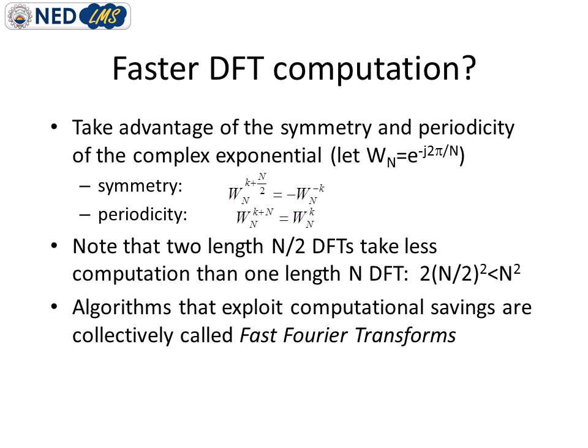A question may arise in your mind: why is FFT required? You can imagine, in standard DFT, as the value of n increases, a large number of computations are required, because the number of computations depends upon n square, as we have seen in the previous slide under the topic of total number of computations.